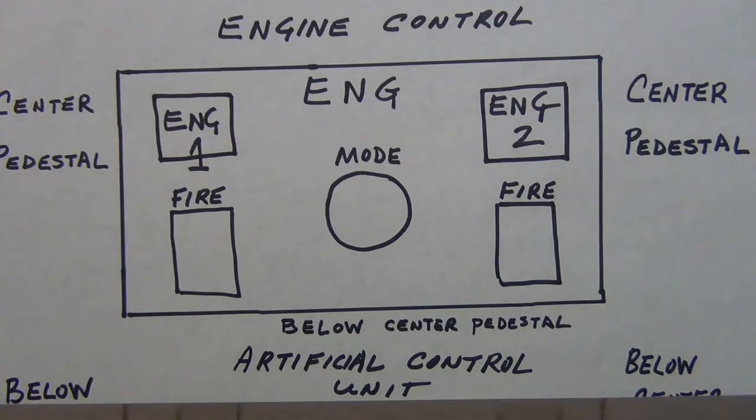Okay. You also have idle stop. Your idle thrust can be selected with one of the detents. That's an intermediate mechanical stop. So that's another position. Remember I mentioned negative 20 degrees TLA, your thrust lever angle. That's reverse. So that's your reverse idle. You have idle stop, reverse idle, you've got your CL, which is your climb, and then I mentioned your flex, maximum continuous thrust, which is abbreviated as FLX-MCT.